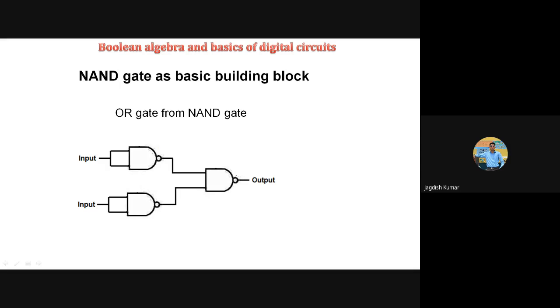0. Very good. So we got one row of the truth table. Whenever A is 0, B is 0, Y is 0. Middle columns let us ignore for the time being. Then let us now make A is 1, B is 0. What will be Y? First let us write down what will be C and D. So whenever A is 1, C will be